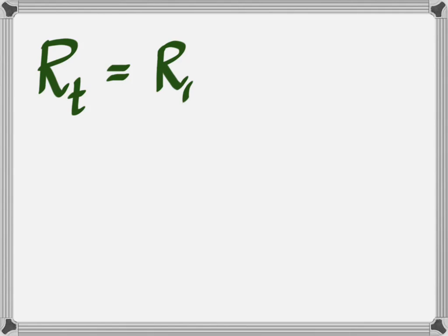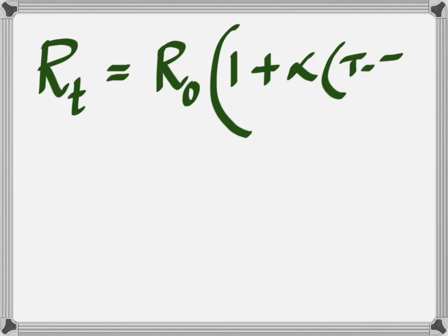Then we also see that the resistance or the resistivity changes with temperature. As the temperature increases, the resistivity also increases due to an increased number of collisions. And the relation is: resistance at T degrees Celsius is equal to the resistance at 0 degrees Celsius times 1 plus alpha (T minus T naught). So once again, resistance is in ohms.